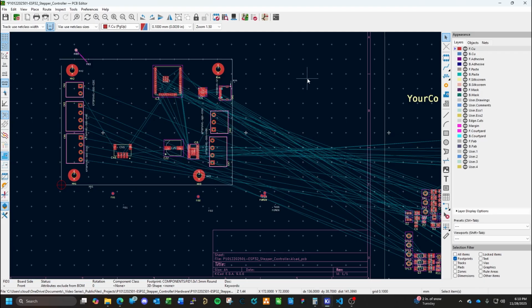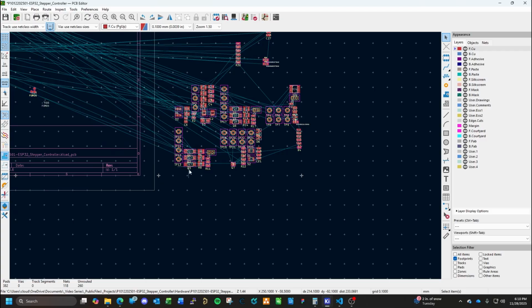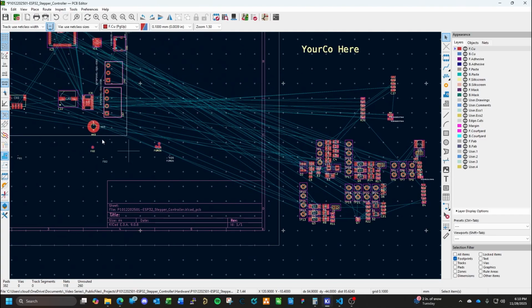Here, let's just arbitrarily throw some stuff together. Again, optos, resistors, a lot of the supporting components can be on the bottom. Like these resistors here can be bottom placed. I decided that I'm going to go ahead and do this as a 6-layer board.